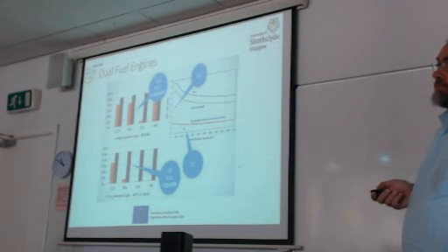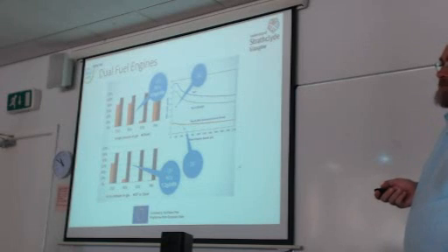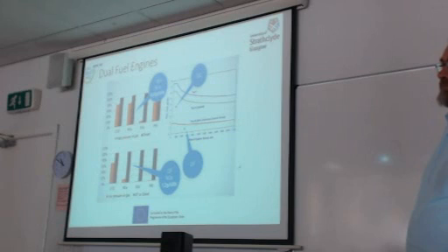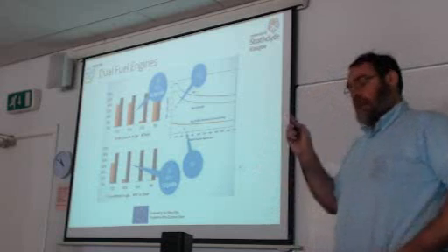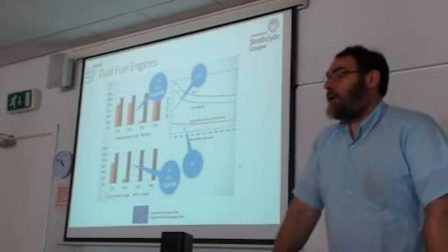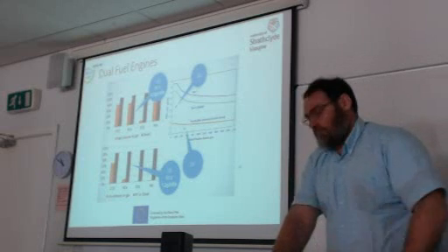I have some understanding problems. As far as I know, the Wärtsilä dual fuel engine system adopted the four-stroke engine for the Otto cycle, but on the other hand, MAN B&W uses the diesel cycle, adopting a two-stroke engine for the dual fuel system. Correct. So the Wärtsilä engines, as you discussed before, have relatively low chamber temperature and pressure. It meets the current regulations. But the MAN B&W engine inevitably uses very high pressure fuel injection. So that is unable to meet Tier 3, right?